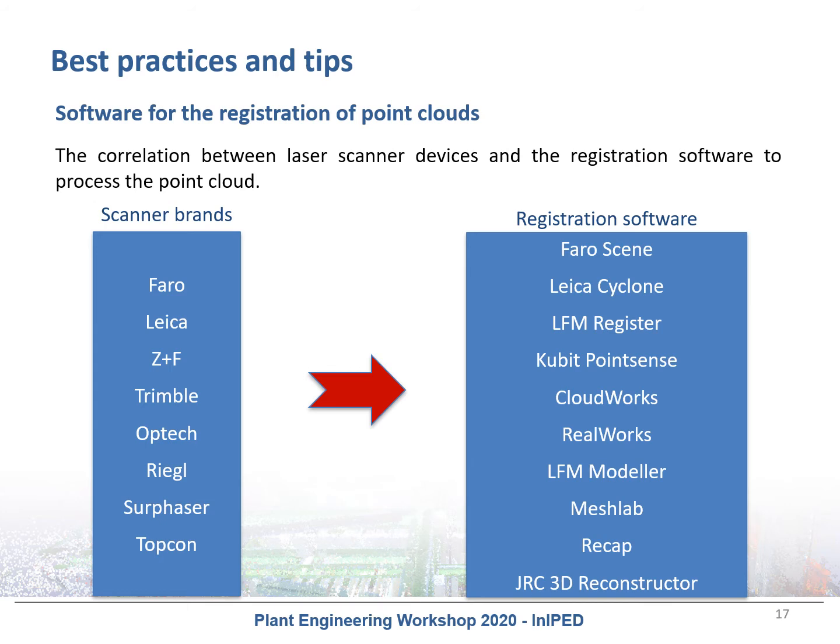I want to show you here the most common scanner brands and registration software you can find in the market. Just to note that there is a correlation between laser scanner devices and the registration software. For instance, if you use a Faro scanner device, you must use Faro Scene for the registration process in order to avoid problems. Or if you use a Leica scanner device, you must use Cyclone for the registration.